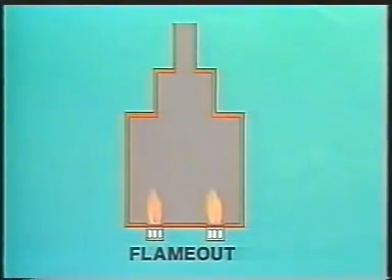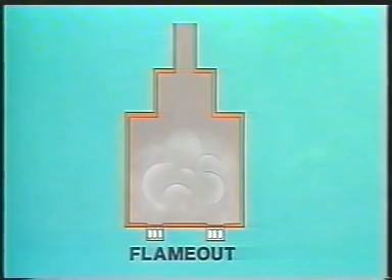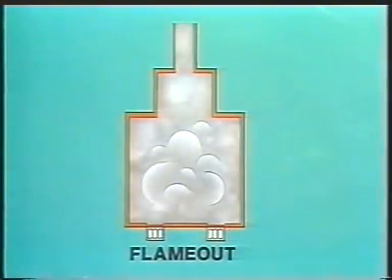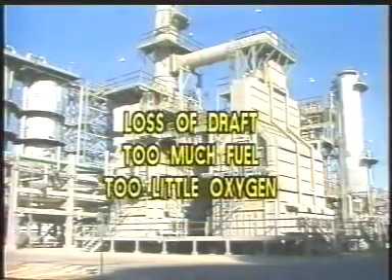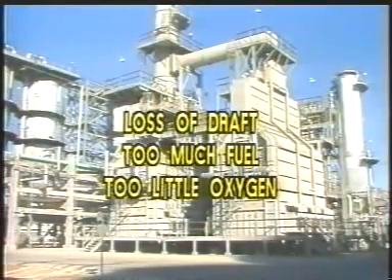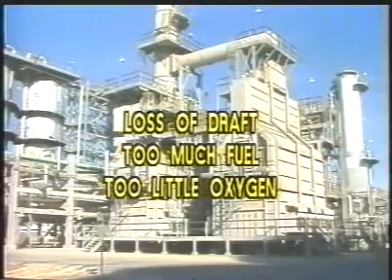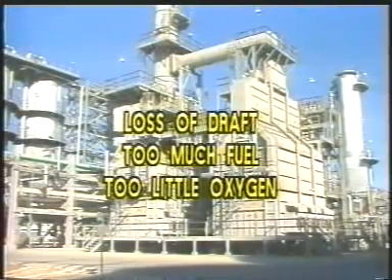Another furnace problem is flameout. This is a situation where the burner flames go out, but the fuel is still entering the burners. When it happens, there is a dangerous buildup of unburned fuel in the furnace, which poses a threat of explosion. So the furnace must be immediately shut down and purged. A flameout can be caused by several things, such as a loss of draft, too much fuel, or not enough oxygen entering the air registers.